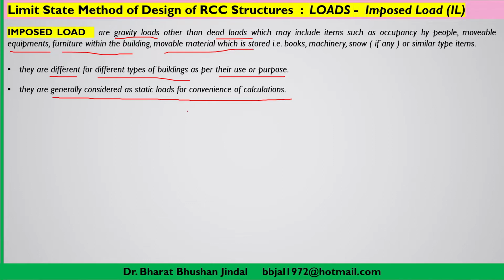There may be a little bit of dynamic effect of imposed load also, but for the simplicity of the calculation, we are not going to take that dynamic behavior into consideration. So you can consider while doing the design calculations, dead load as well as imposed load, they both are taken as static loads.